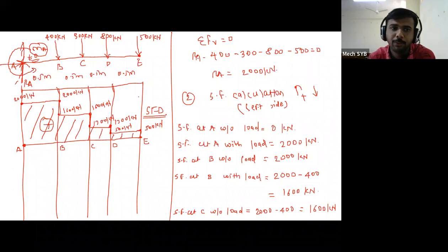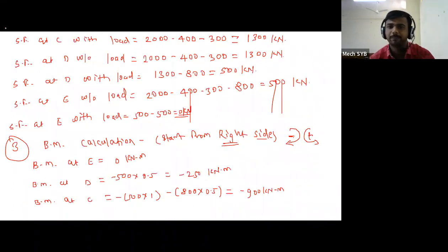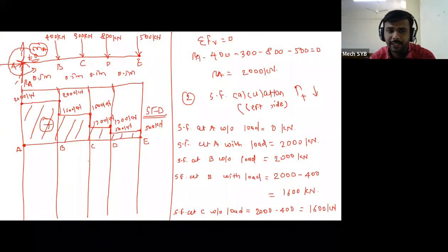But if you think about the simply supported and overhanging beams, in both those beams the bending moment at the end point is always equal to 0. Okay, so now you have to draw the figure. If you look at all the values of BM, all values are negative. Therefore your BMD will be in the negative region only.